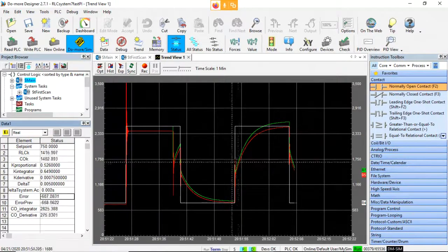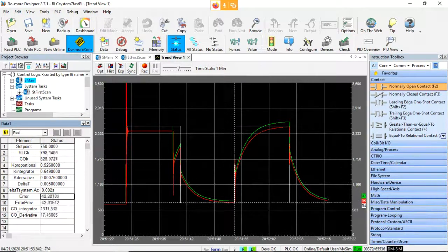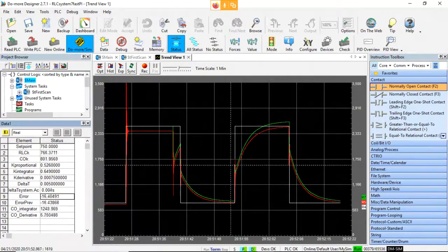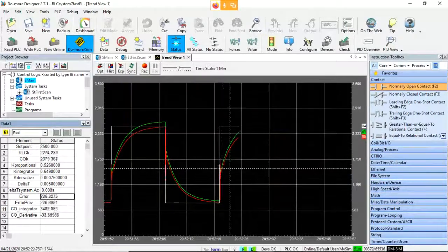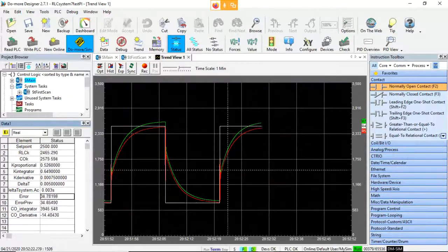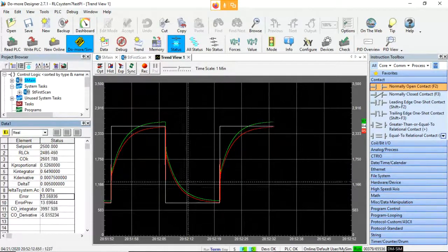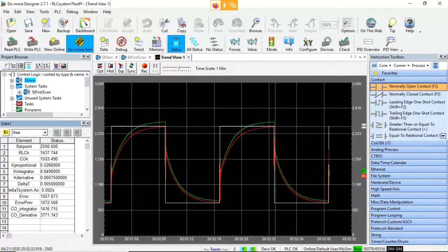Now there is a little bit of ringing when it changes here. There's a little bit of ringing because it's a fast system and it's going to bounce around. And so when you give it a drastic change, which a step change like this is, we're just stepping up and stepping down, there is definitely going to be some ringing here. But you can see that we've really cut out that ringing. It's not ringing way up here to 5,000 like it was before, or way above 3,500 anyhow. And then you can see that the red, which is our actual output, is getting real close to that.